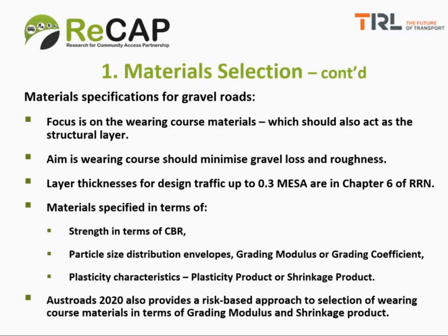Now, for gravel roads, the focus of material specifications is on the wearing course. And the wearing course also acts in most cases as the structural layer. Now, the aim of selecting or specifying materials for gravel roads is to minimize gravel loss and roughness.